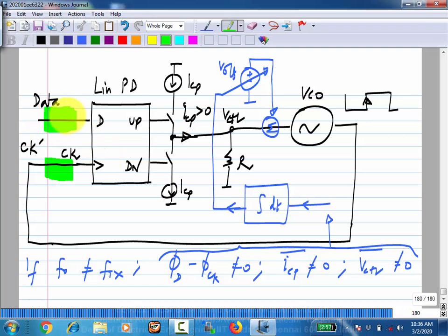It will settle to a phase offset. Basically, the steady state phase offset is what is not 0. Okay. So now, essentially what you have to do is, you have to set a particular value of V offset. You have to let this settle to steady state, look at the phase difference. If that is not 0, you try a different value of V offset and so on.